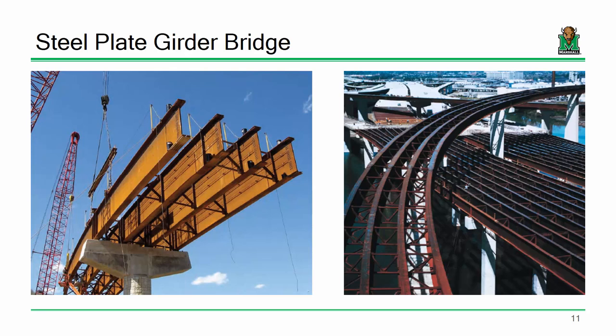Well, during each one of those stages, that beam, that girder, is seeing some amount of stress. What's kind of interesting is when you find bridges like this, these really funky bridges with crazy geometries and crazy skews and what have you, sometimes the worst case scenario in terms of stress is actually during construction. In other words, the most unsafe region throughout the whole process is during the construction.